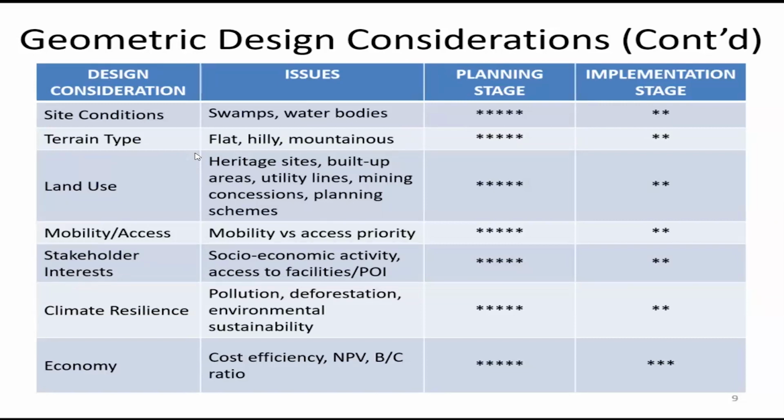If at the design stage, there didn't appear to be the need to connect a residential area to the road we are designing, we have to look at it again during implementation. We may realize that we have to provide connections or modify the alignments to facilitate access, so we don't kill settlements or their livelihoods.